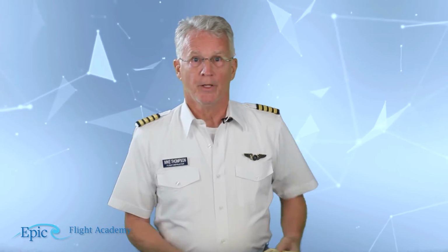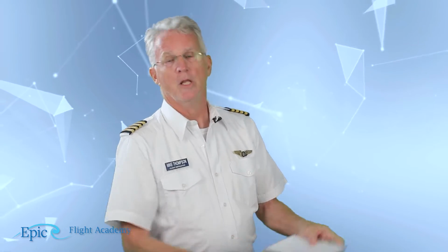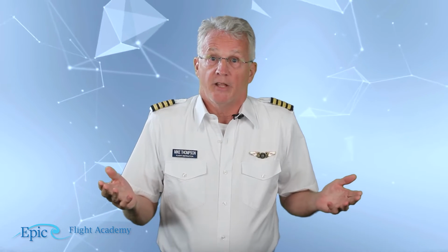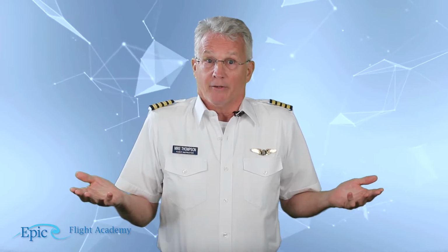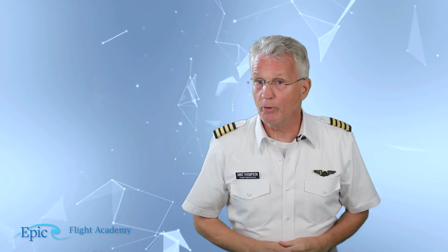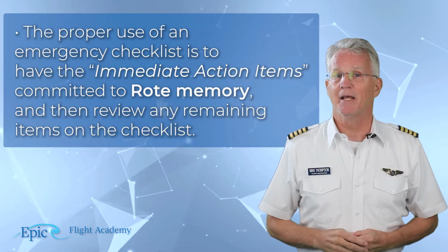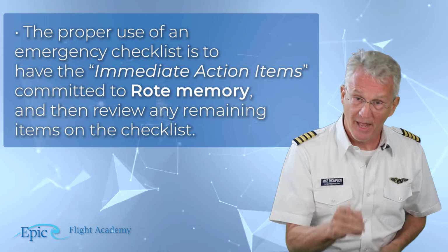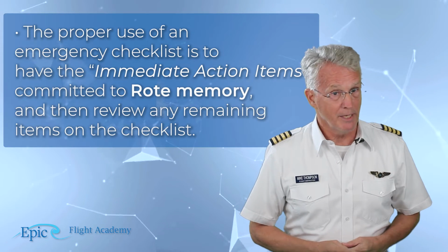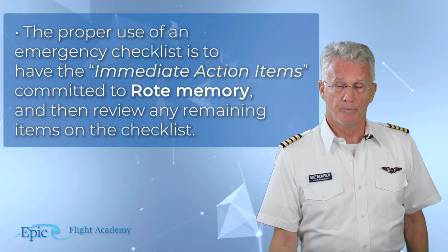In an emergency, I don't want to be fumbling around for that checklist. Response number 2 is also an improper use of the checklist in that I ignored it altogether because I did not have my immediate action items memorized. So the proper use of an emergency checklist is to have the immediate action items committed to rote memory and then, time permitting, review any remaining items on the checklist.